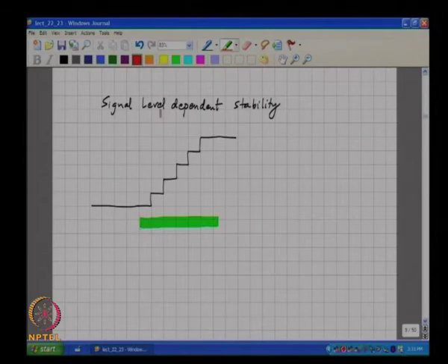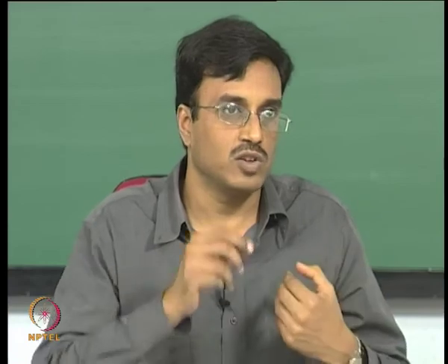Clearly if this is the range of the quantizer, the input cannot occupy the full range of the quantizer, it must be smaller by some amount, because you must leave some range for the shaped quantization noise to wiggle or ride over the input.